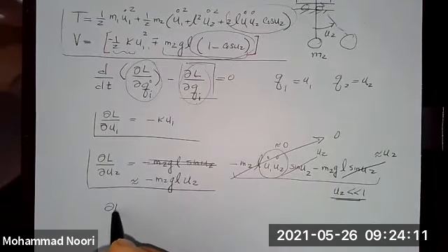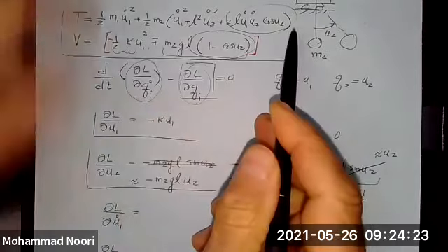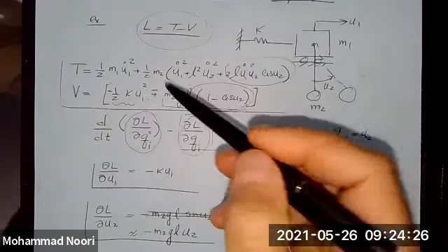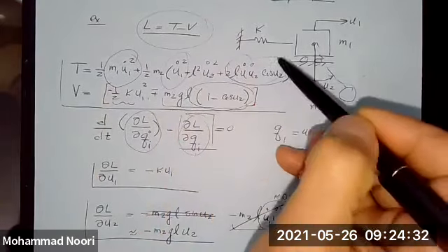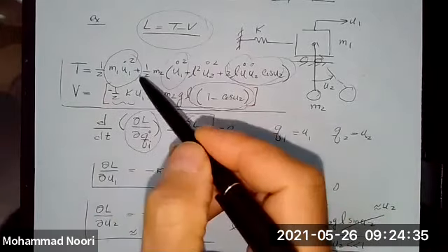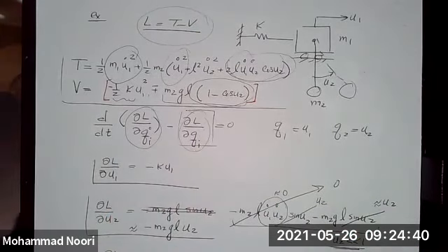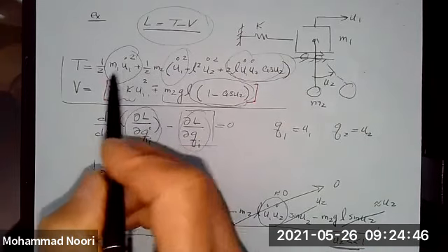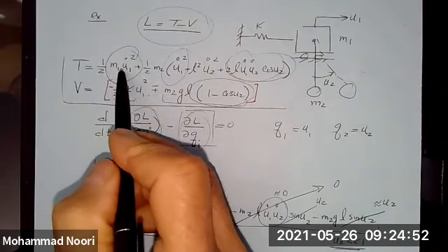So this is the partial derivative with respect to the two displacement terms. Now you need to take the partial derivative with respect to the two velocity terms, u dot 1 and u dot 2. So again, the only variable is u1 dot. Consider that u1 dot is X, so you have 1/2 m1 X squared. So it would be 2 times 1/2 times m1 X.